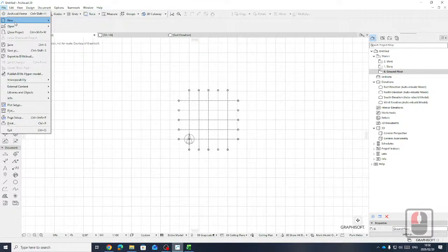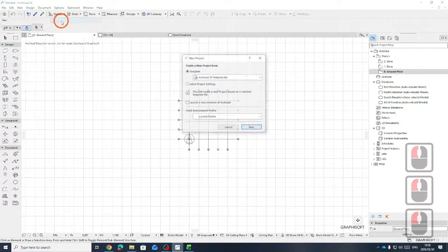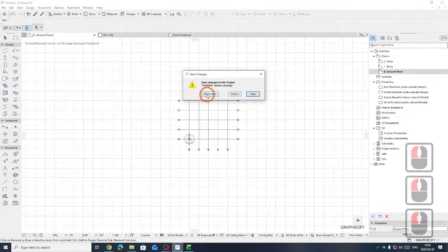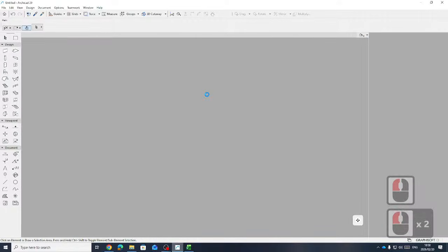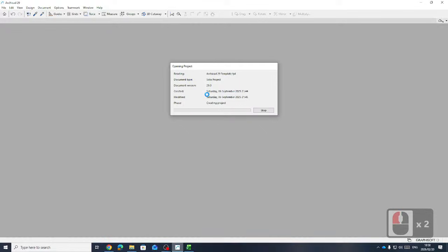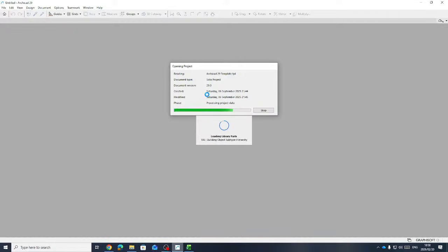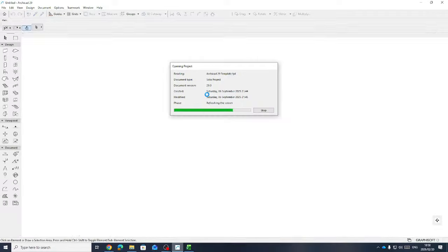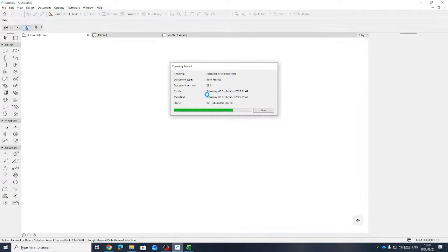Okay, so it's actually very simple. Very, very simple in Archicad, actually. Okay, so last year, I tried to stress to everyone that your grids and your levels or stories drive the whole project. So if you don't set up your stories correctly or grids correctly in the beginning, the whole project gets very difficult going forward. The structural grid and stories actually drive the whole model in theory.